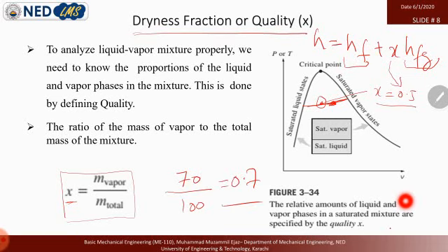It's very simple. But in an experimental setup, there is some apparatus which calculates this mass of steam. It is not very easy. By the formula it is very easy, but actually calculating this is hard. In the initial state you can weigh the water or calculate the volume of water, so by the density you can get the total mass. But calculating the vapor is very different, and we have a special apparatus to calculate this vapor. Anyway, by definition it is the ratio of mass of vapor to the total mass of the mixture.